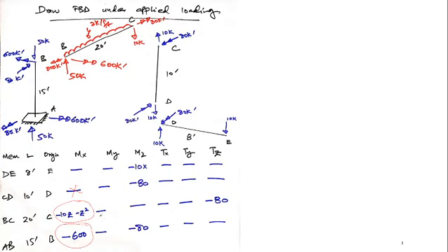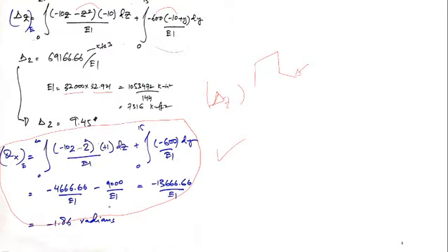So respective values have to be multiplied, and I've done this. 10z minus z square is multiplied with 1, and then again 600 is multiplied with 1. Okay, so I've got this value. You should know that this is kip square foot. Here it was kip cubic foot. Divided by EI, the unit of EI is kip square foot as well, so units would be radians.